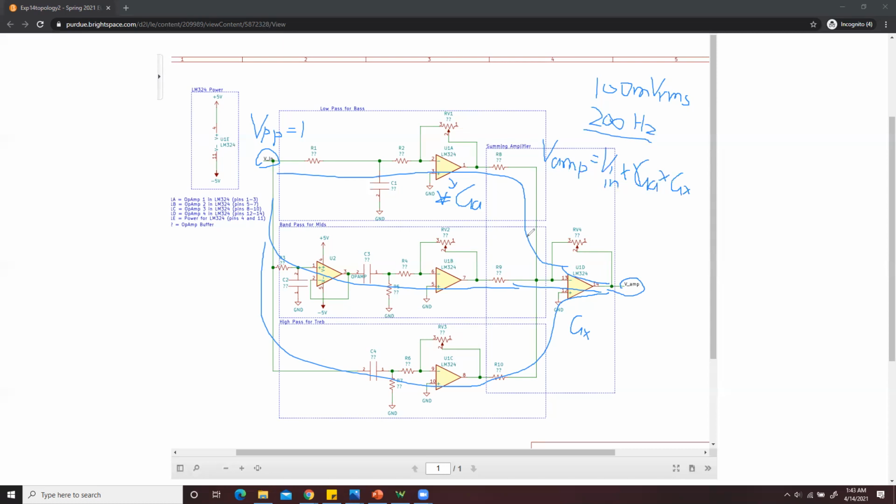And then you also want to check the gain for 2K hertz, and that depends on this amplifier and this amplifier. But the calculation process will be similar. The total gain is simply this amplifier's gain times this one, for each different frequency. All right, so that's how you can get the values for those resistors, and you already calculated the values when you decided the cutoff frequency.